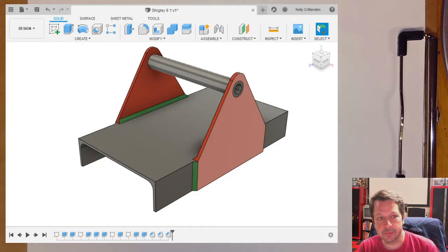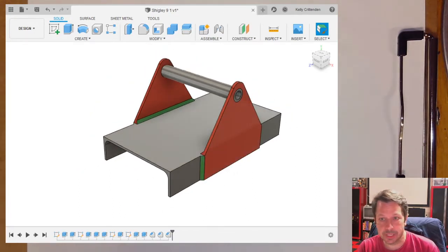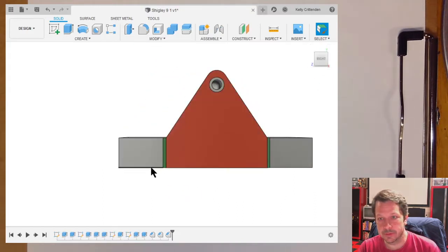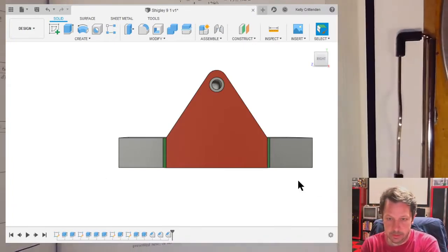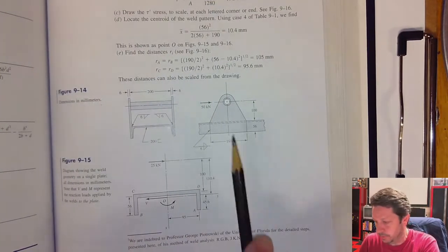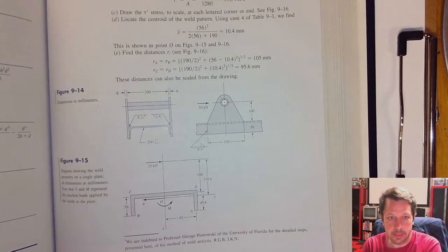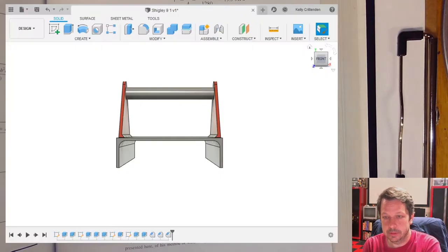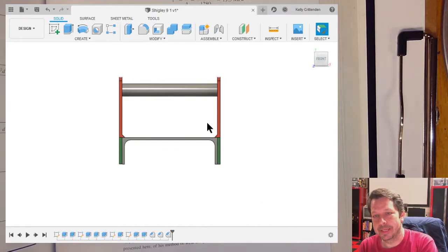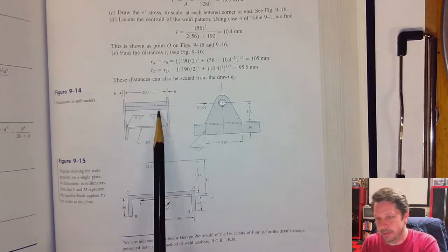So this is the 3D version of the channel, the gray channel down here at the bottom. The plates on the side, I colored them red. Here's that tubular feature. So this view is basically telling us what is going on right here. And if we look at this view, this one has perspective turned on, so you can see the sides coming in. I suppose if I turned that off, you would... I don't remember exactly where to go to turn that off now. Let's see, I think it's in the camera. Here we go, there's orthographic. So there is the view that's given right here.